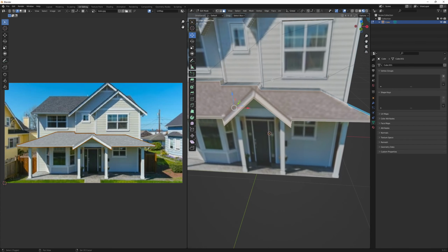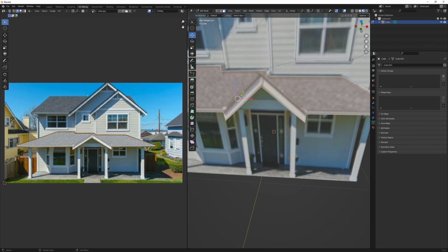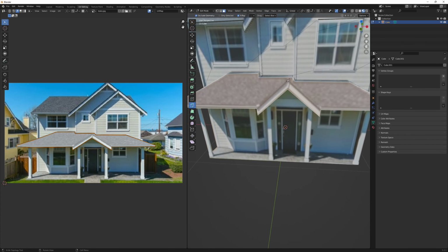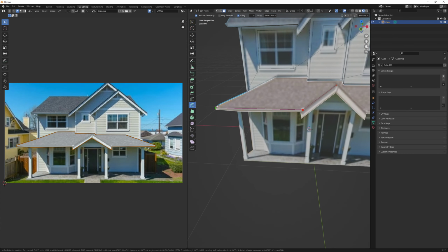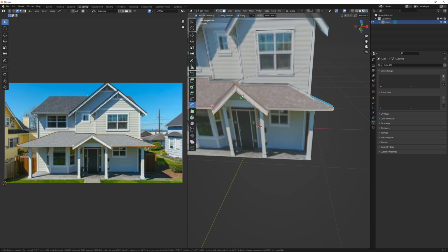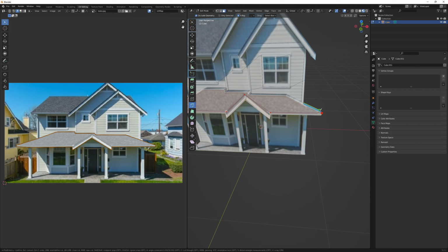So what we're going to do now is select this apex of this building here. We know this is the roof, so we're just going to follow this down to about there. And again, I'm holding Control to make sure it doesn't snap anywhere. Making sure that is what we want. Just like that. And I'm going to right click and press enter.